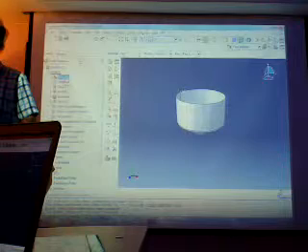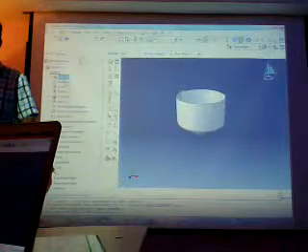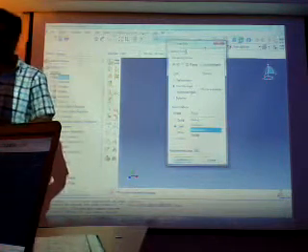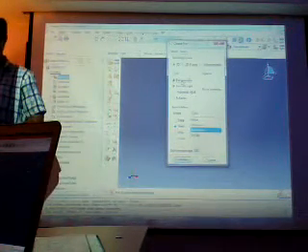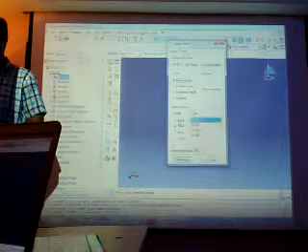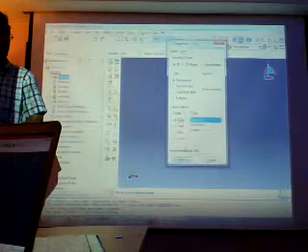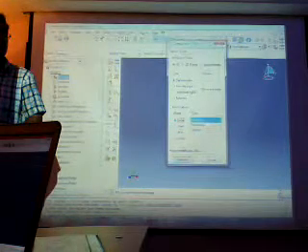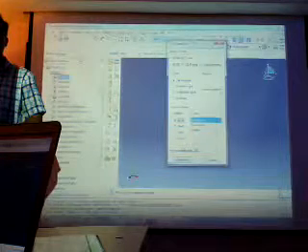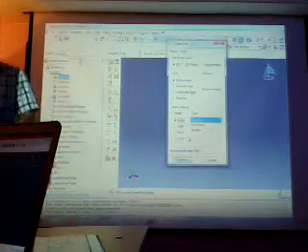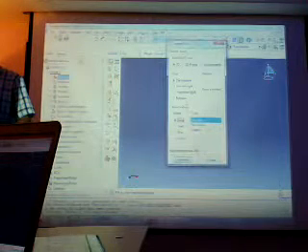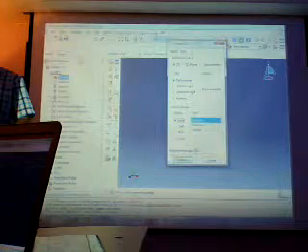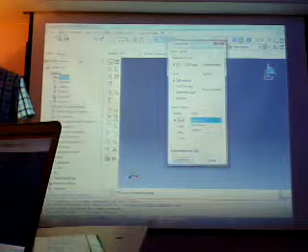Now we are going to create a second part. The second part is the billet, that's 3D, deformable. And that was the missing part in assembly. When we make 4 parts, we should assign a reference point for each part. So we forgot that step. That's why we can assemble them. So that was the missing point. For each part we should assign a reference point.